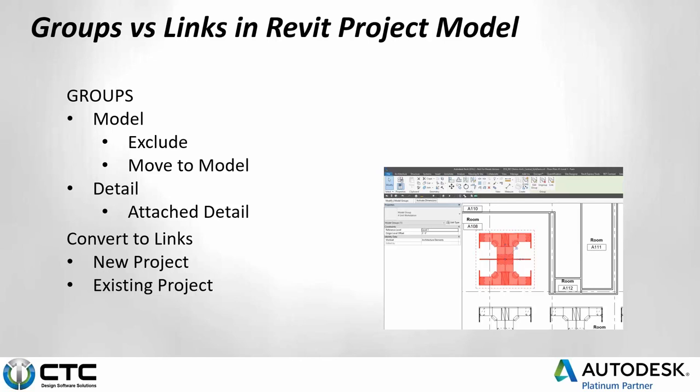So it's really handy to have that, and then edit one group and it edits all of them that are that same group. This is a very useful thing for furniture layout, and also it could be used for apartment buildings and hotels that have common unit layouts. We can group the unit and then be able to use that unit wherever we need to in the project. And I have some samples that I will show in this process of what you can do and potential issues you might run into with these types of groups.